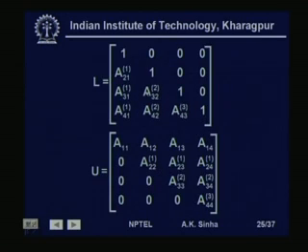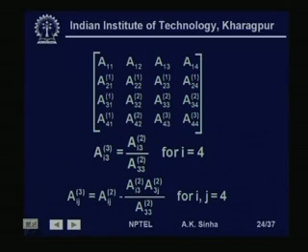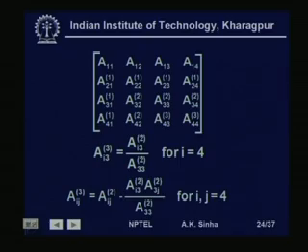And then if we do this, then we have a factored matrix here, where the upper triangular elements are same as what we get in case of a Gauss elimination, and the elements below the diagonal are the factors that we need for processing of the B vector or the vector of the mismatches.